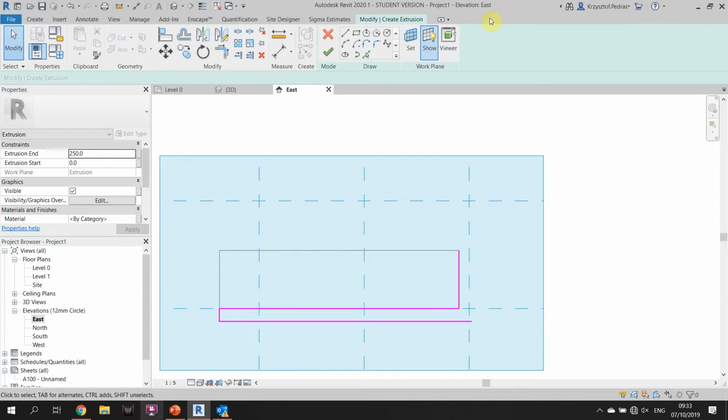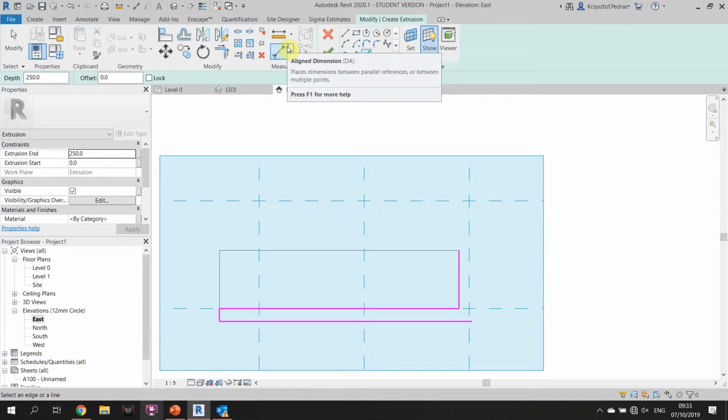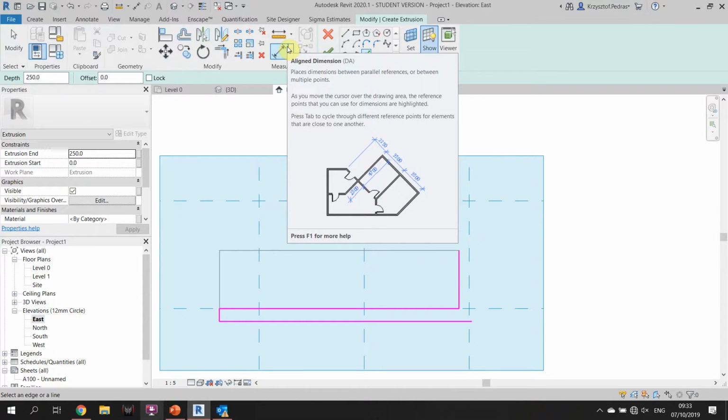When we're at this point, we can either model it by normal line, or we can still use a pick line even though we can't really pick the line, simply because we have an option of offset, meaning that we can pick a line, but the line that we create is gonna be a certain distance that we specify from the object that we click on.